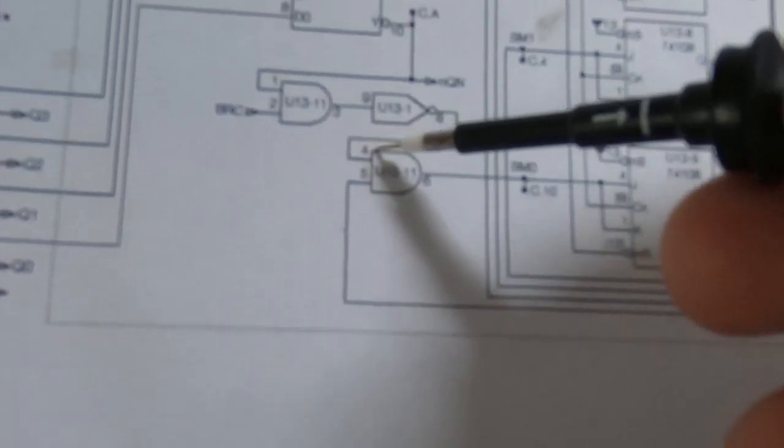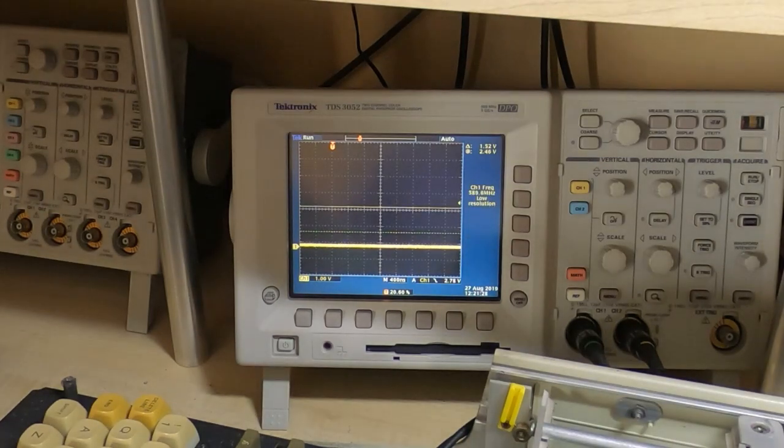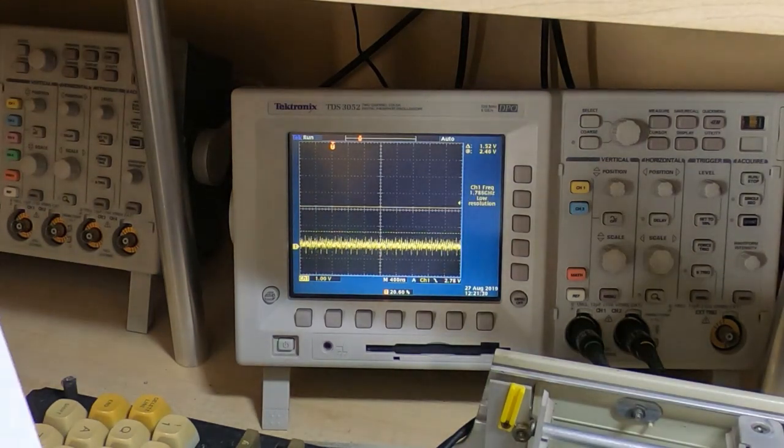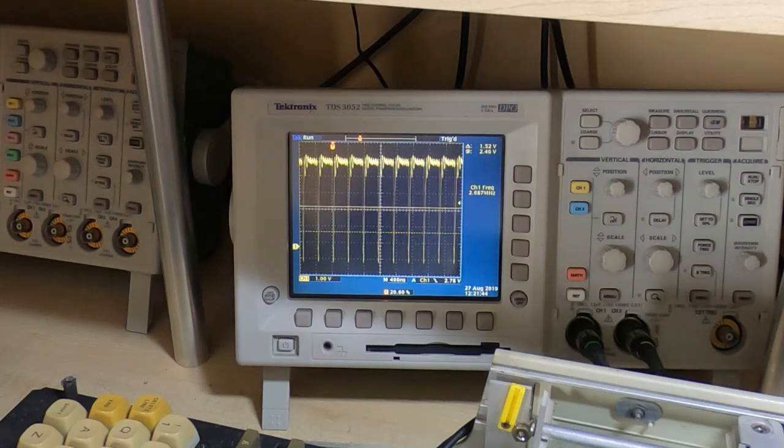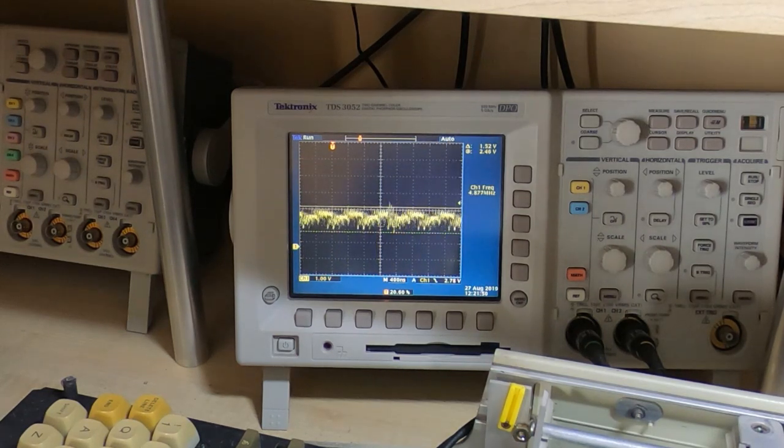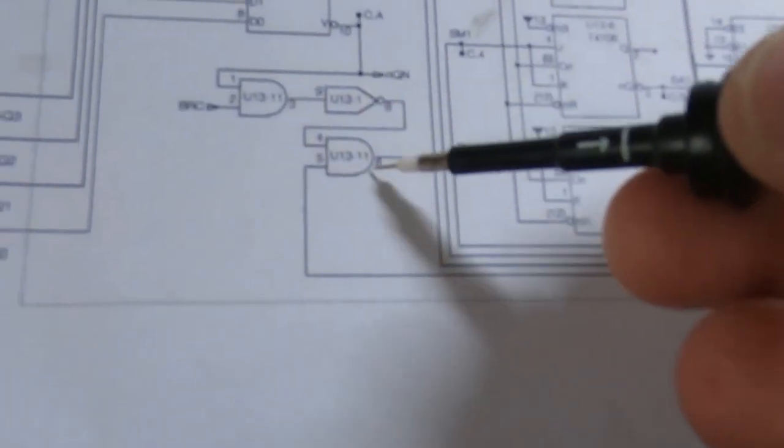So we'll look at this gate. So pin 4, and that's correct, the output of the inverter. Pin 5 is the value coming from the ROM, so this is the bit we're trying to XOR into the address, and that looks correct. And then the output of that gate is again incorrect. So the outputs of both of these gates are not doing what we would expect.